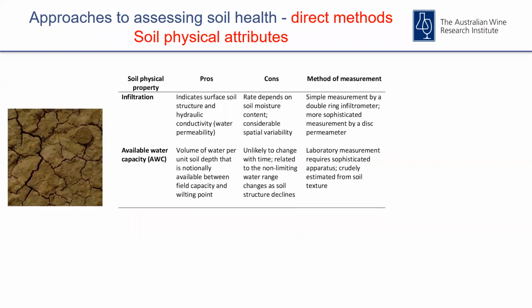The last couple of soil physical attributes: infiltration, obviously important for understanding soil structure and the hydraulic conductivity. But at the same time, the rate depends on soil moisture content, and there's considerable variability across an individual site.